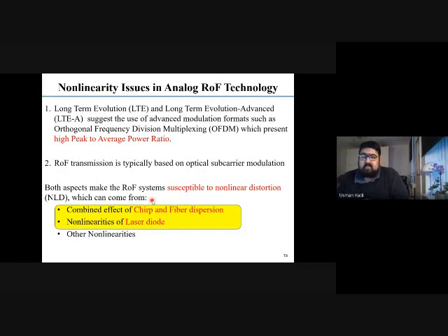The basic nonlinearities in the system can be divided into the combined effect of laser chirp and fiber dispersion, and the nonlinearities of the laser diode and other nonlinearities. So basically, we would like to compensate the first two highlighted parts, which are the combined effect and the nonlinearities of the laser diode.